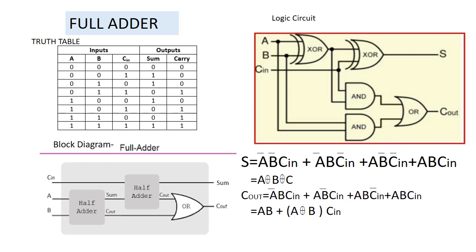So, in the second and higher columns, the two data bits of that column and the carry bit generated from the addition in the previous column need to be added. This requirement is met by the full adder. A full adder adds the bits A and B and the carry from the previous column, called the carry in or C in, and it produces an output as sum bit and the carry bit, which is called the C out.